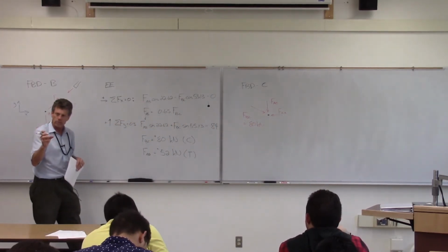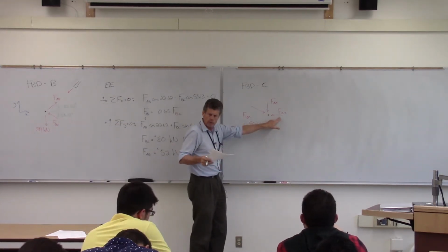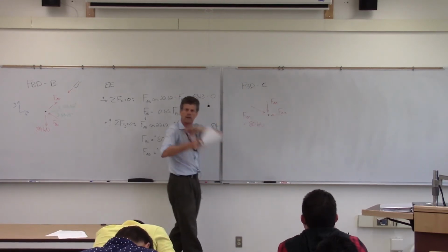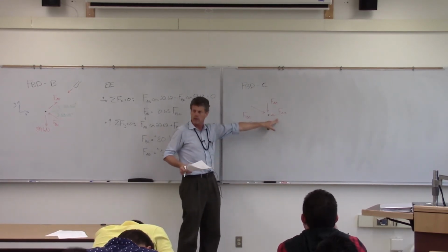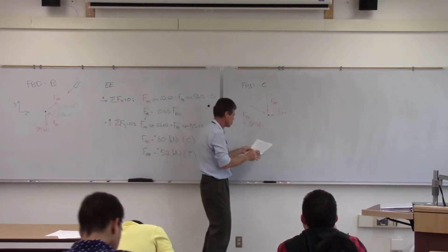So when you get to places where there are supports, and this is the nice thing, when we talked about that 3rd step, you can check it. You can solve for the support forces of the entire truss. And did you get the same result as you did through the joints method? So it's another nice check there.